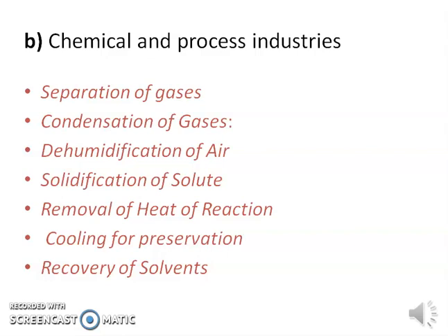In petrochemical plants, temperatures as low as -150 degrees centigrade with very high refrigeration are used for separation of gases by fractional distillation. Some gases condense readily at low temperature from the mixture of hydrocarbons. Propane is used as a refrigerant in many of these plants for the separation of gases.